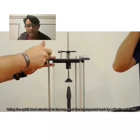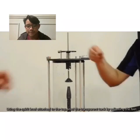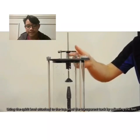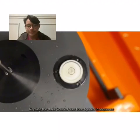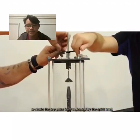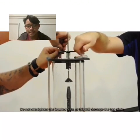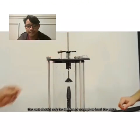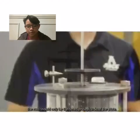Using the spirit level attached to the top, level the transparent tank by adjusting the feet. Replace the 3 knurled nuts, then tighten in sequence to retain the top plate level indicated by the spirit level. Do not over tighten the nuts as this will damage the top plate. The nuts should only be tightened enough to level the plate.